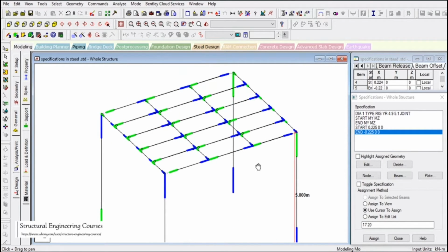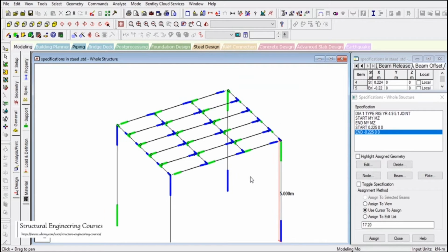If we want to fine tune our bending moment and shear force results, then we need to do these offset command specifications. And one more thing that I'd like to add here, you can press Shift plus E on your keyboard again to switch off.